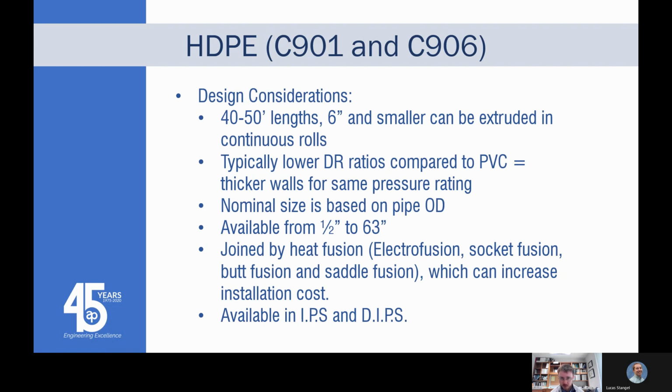The only other thing I was going to mention about HDPE, more of a construction consideration than a design consideration: we had a sewer force main out in Cove, and the contractor was putting the butt joints together. He had his trench excavated and was putting together long runs, hundreds of feet long. Something unique to HDPE, a lot more than PVC, is that it'll walk on you. That pipe will expand and shrink with temperature change. It's pretty sensitive to that. So we had to be cognizant of getting it in the trench and buried, especially in Northeast and Eastern Oregon, where we get cold nights and hot days. Usually not a huge deal, but worth mentioning.